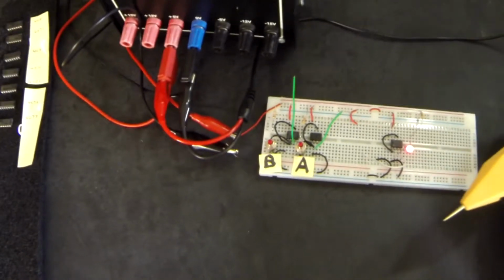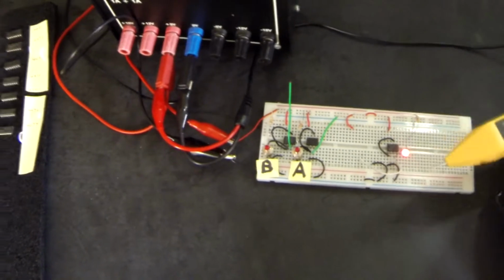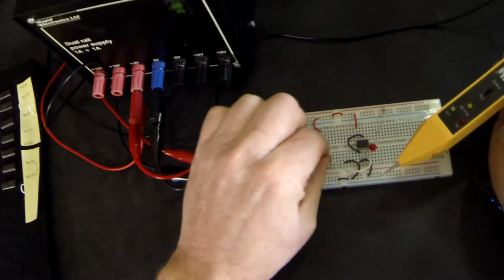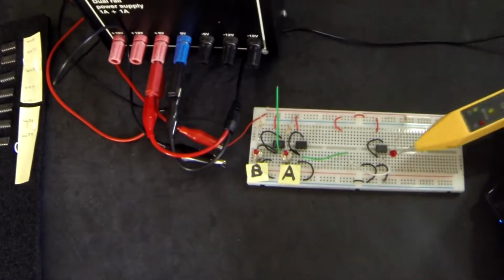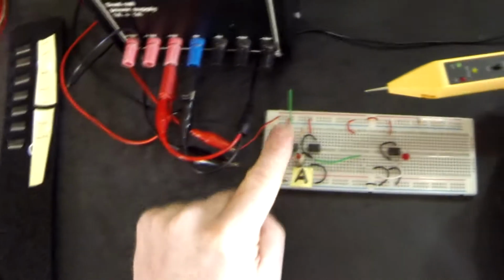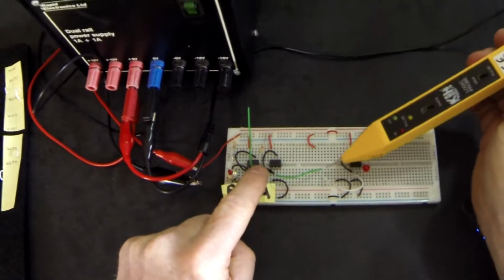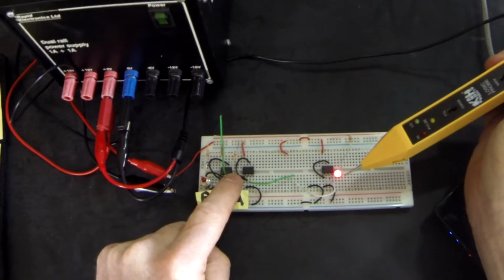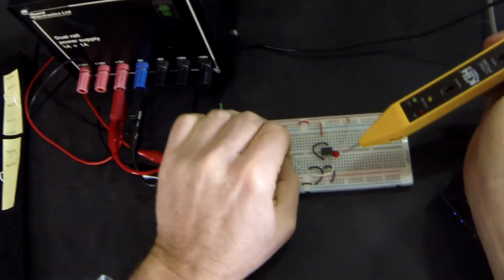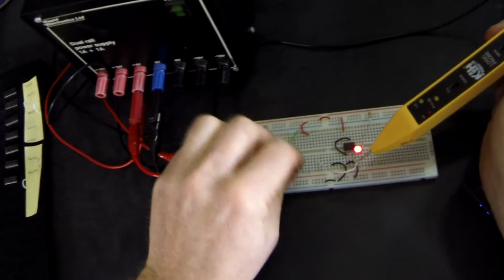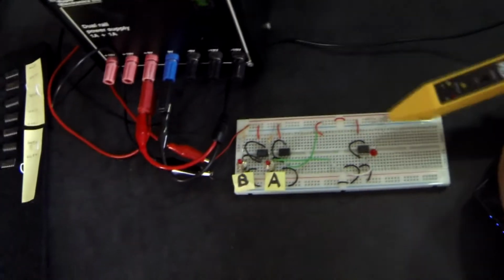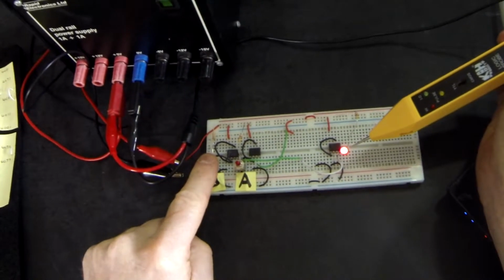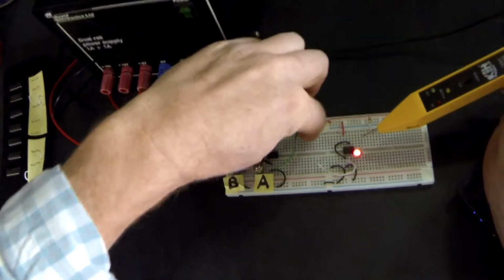So what I can now do, you will see that the LED here is on, but I don't actually have a signal going to my output circuit. So I'm going to connect switch A to my output circuit. You saw the LED went off because my switch is unpressed. So when I press the switch, it sends a high, therefore the LED should come on. I'm going to disconnect that and connect up switch B and check that B and the output circuit work. Good. So I now know both my input circuits work and my output circuit works.